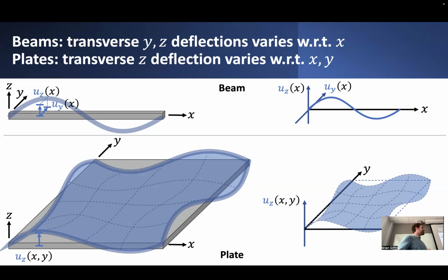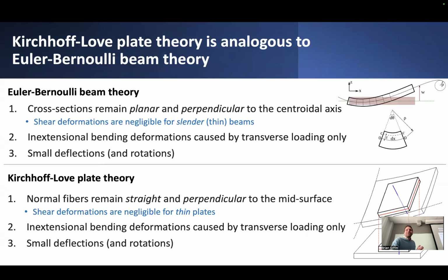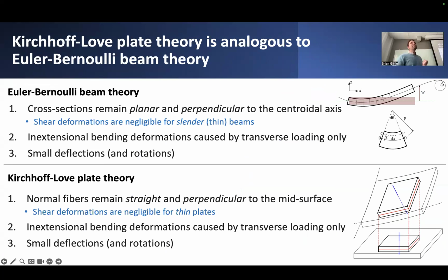But to really set ourselves up for success, we need to establish more rigorously what exactly is this beam theory or plate theory that we should be using, and what exactly are these assumptions. Well, we already know beam theory, and we've already established the fundamental kinematic assumptions of beam theory. In particular, I'll distinguish Euler-Bernoulli beam theory, which is what you probably think of when you think of classical beam theory. And it comprises those two fundamental assumptions that we previously stated.